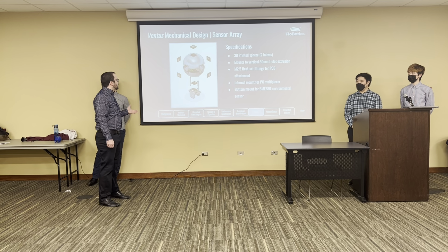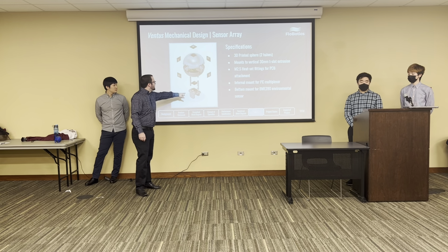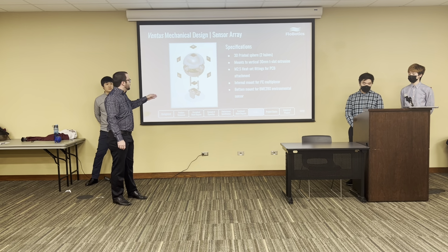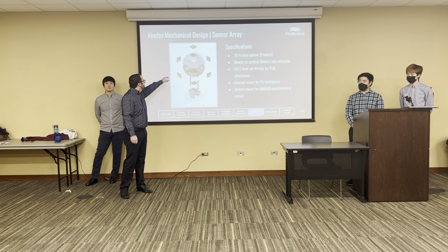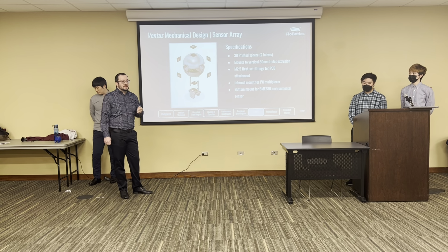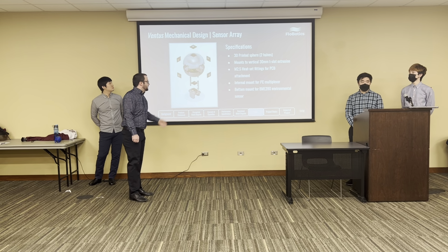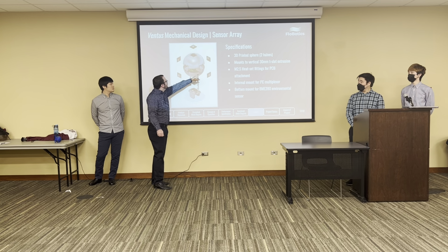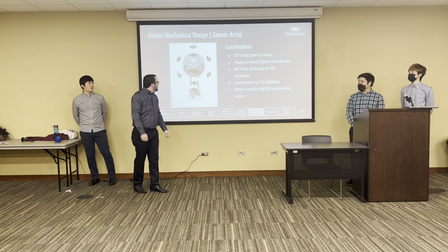Now here is our sensor array, which we mount our 6 PCBs to with our PAV 3005Ds. You can see on the bottom, this bracket mounts to our vertical extrusion, and then it holds the BME 280, which is in series with the MUX chip on the inside of the sphere. This MUX chip connects to all 6 sensor PCBs. And we did that because the PAV 3005D has a set I2C address, and we can't change it, so we need to be able to cycle through all sensors to get readings. And then everything's held together with heat set fittings on the insides of these holes, and when it comes together and you screw the PCBs down, it's one solid structure.